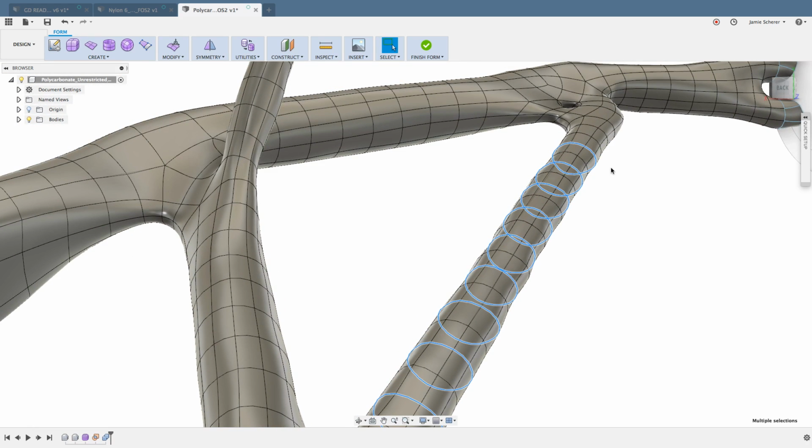So I'm going to grab those edges, I'm going to hit delete on the keyboard, and you'll see instantly, there it goes, the T-spline is automatically updated, right? It's one of the beauties of working in the Sculpt workspace that it always maintains G2 continuity, which means that the transitions between the faces and edges are always perfectly smooth. No seams, they stay perfectly continuous.